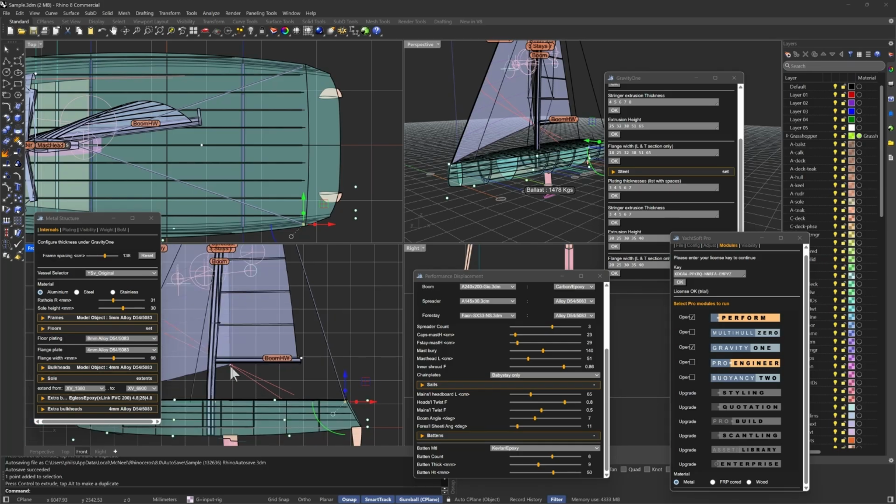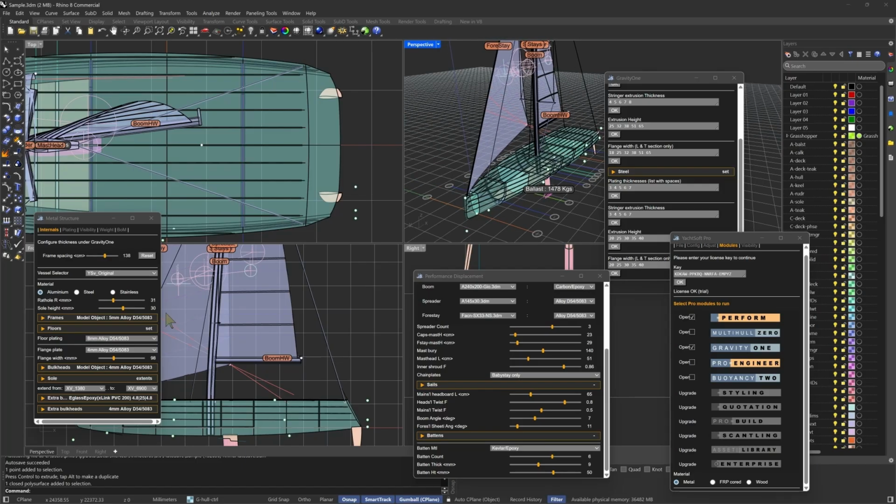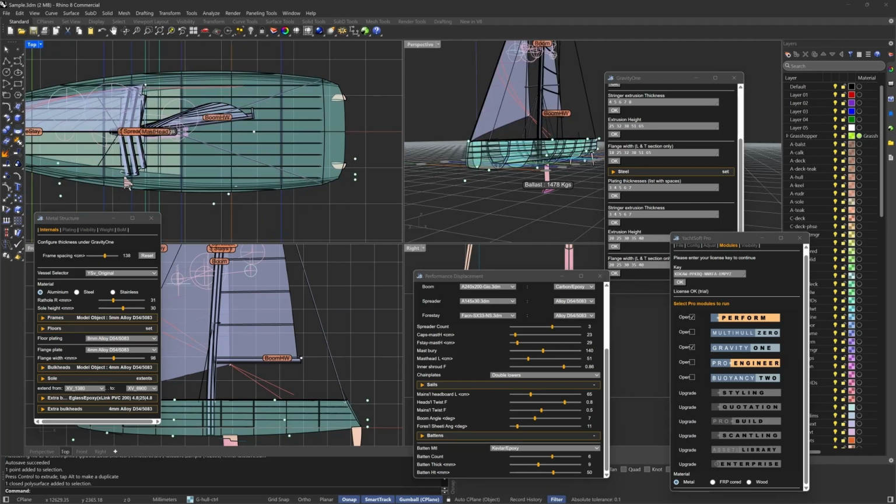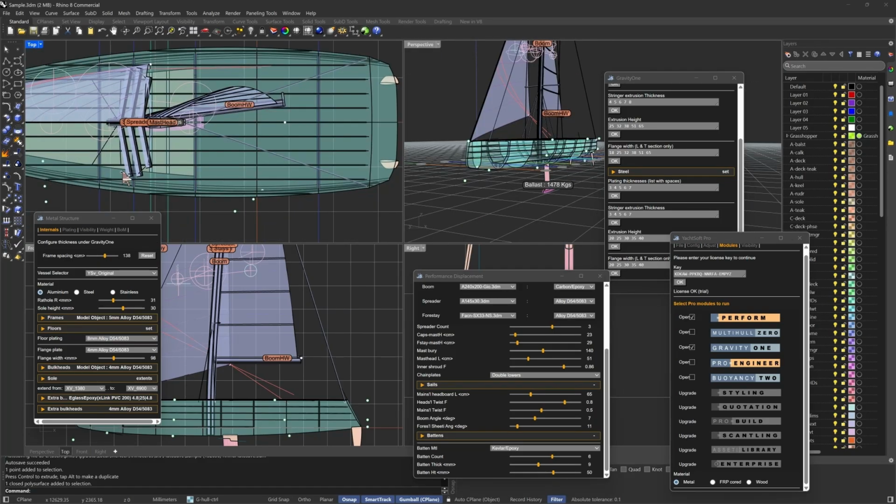So at the moment, this is again a multi-hull rig, so we need, say, double lowers, which are more realistic than this. And then let's just make the spreaders a little bit wider. So that's the chain plate position for the diamonds. Just have to grab that point. I'm going to move it out to that frame, out to the side of the boat.